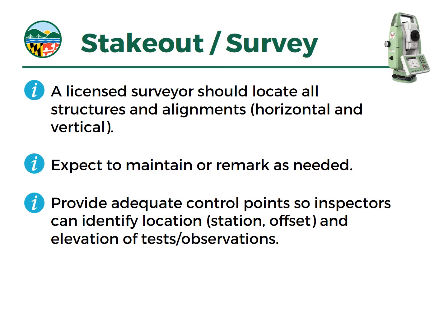Okay, I'll touch on this subject briefly, but we've had a project recently in Maryland where the contractor on the site thought they could eyeball the location of a manhole on the plan set. They ended up being like 20 feet off of the location. They required extensive additional excavation, and then they had a grade bust. So the pipe had a reverse slope back towards the dam and didn't drain well. That all could have been saved with a real simple call to your surveyor.